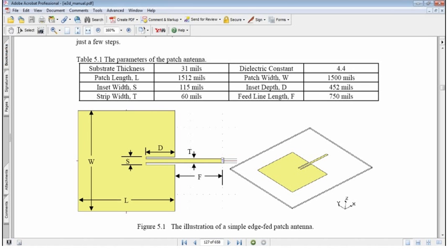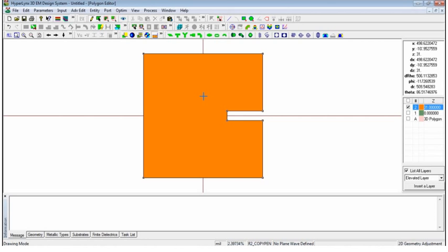So I will window these two vertices, and after that in the advanced edit option there is an option for continuing the straight path. If you go to continue straight path, it will ask for the path length, which is 1102.